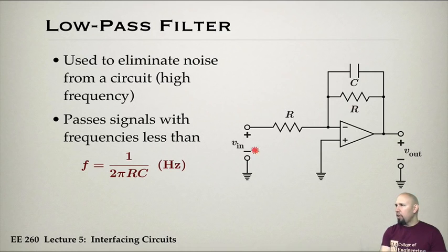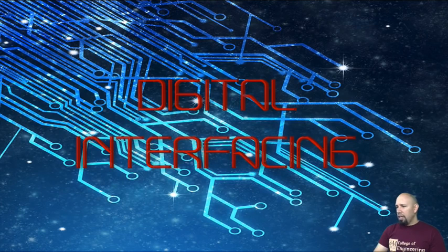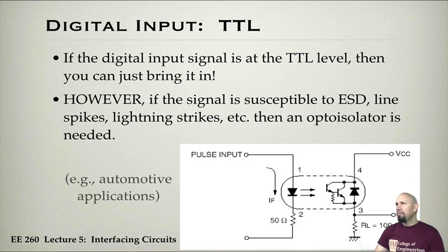And this is actually what's called an active filter. There are also passive filters, but they don't work nearly as well, or more particularly, they create loading effects that are not that desirable. So, okay, that's the analog stuff. Let's move on to the digital interfacing.